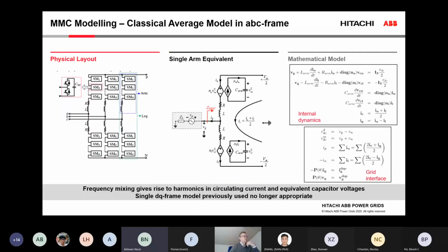Yeah, so I think so. The whole thing starts basically with that you want 50 hertz here on the grid side. You create a voltage reference that you feed into the modulation index here that is also primarily 50 hertz. We may be using third harmonics and so on, but for simplicity, it's only 50 hertz.